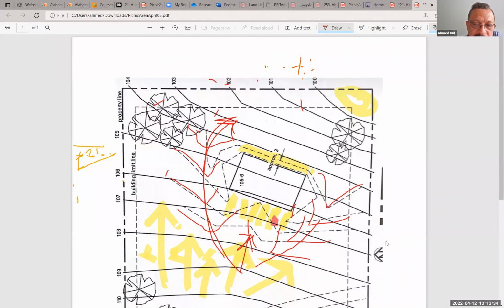And as I'm drawing here, this can be done in different shapes and forms, depending on how much you would like to dig and how much you would like to add soil. So, cut and fill. The cut and fill at the end should be equal, because you don't want to move earth out of the site or bring earth from outside. You need to make cut and fill almost the same. Every line like that, if it is a different line, means a different volume of cut and fill. It might not go like that.